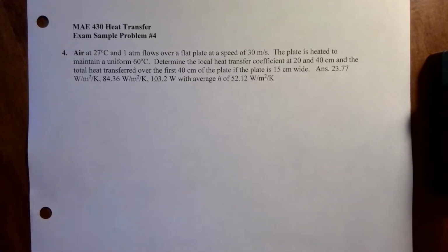These examples come from previous exams and are in the sample problems I've provided for you. Air at 27 degrees C, 1 atmosphere flows over a flat plate at 30 meters per second. The plate is heated to maintain a uniform temperature of 60 degrees C. Determine the local heat transfer coefficient at a distance of 20 and 40 centimeters from the leading edge, and then find the total heat transferred over a 40 centimeter long plate. In this situation, it happens to be 15 centimeters